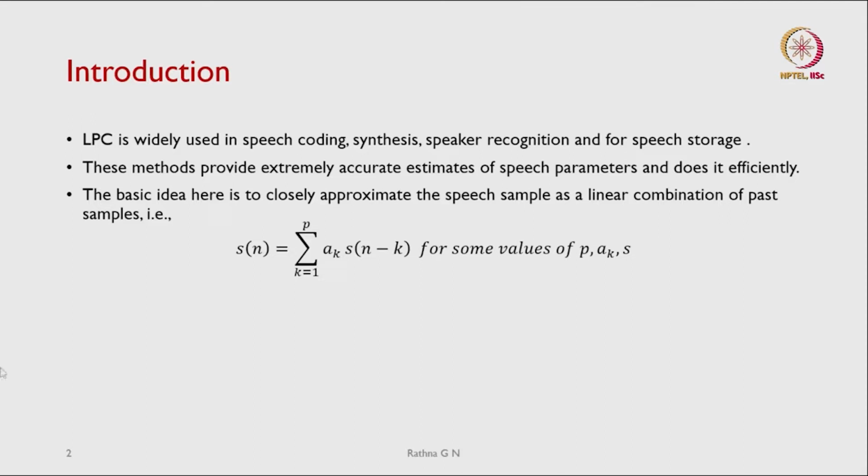As you can see in the equation, s of n is the present sample, k goes from 1 to p, a_k are the coefficients, and s of n minus k are the past samples. So, for some values of p and a_k, we will be predicting s.